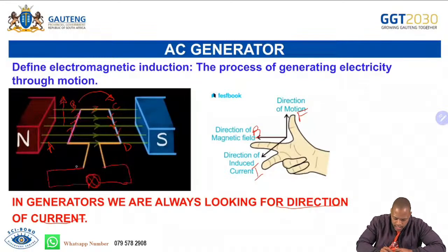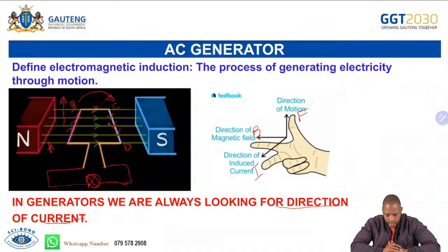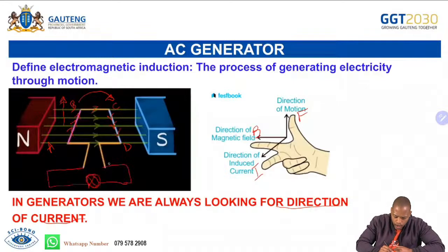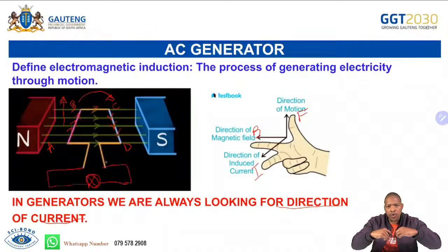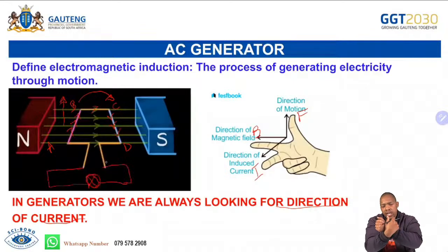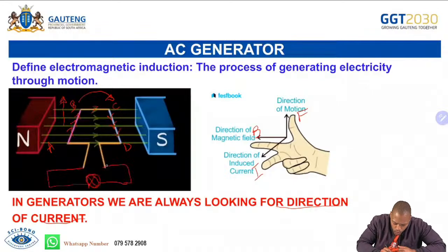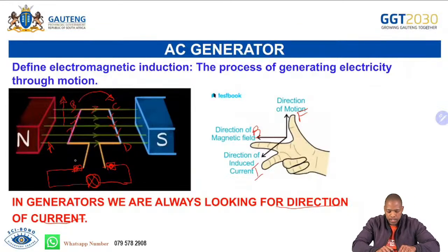Therefore, that's why they decided to say, let's not connect these wires directly into the coil. Instead, let's have something that is just simply going to touch the coil, making sure that it's maintaining electrical contact between the load and the coil. So what they used for that, to avoid these wires having to twist and turn and tangle with each other, they used the carbon brushes. They are going to put brushes here, which are called carbon brushes, right?